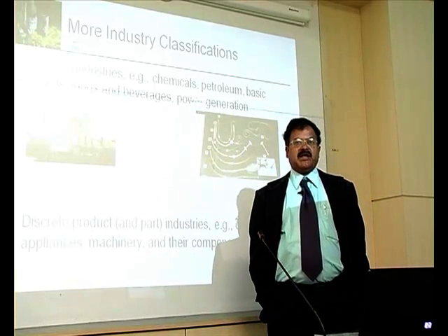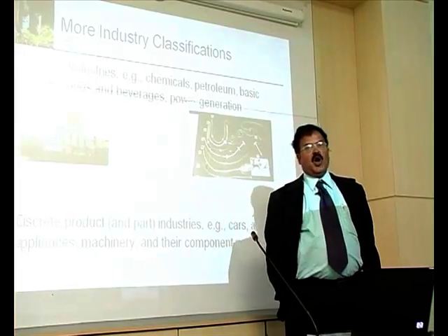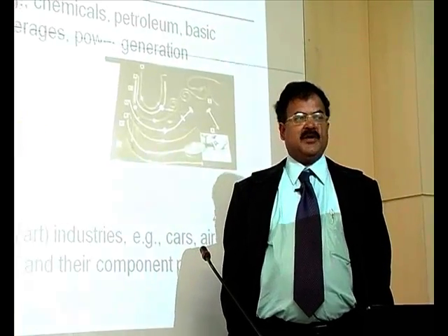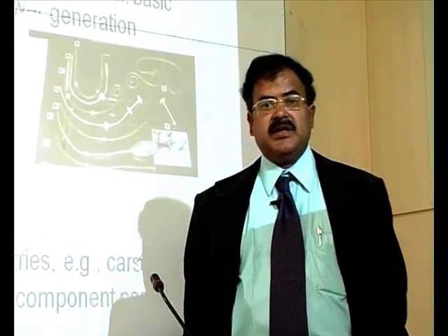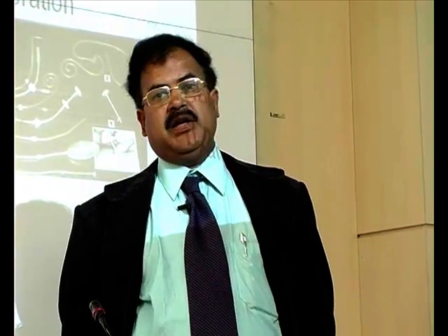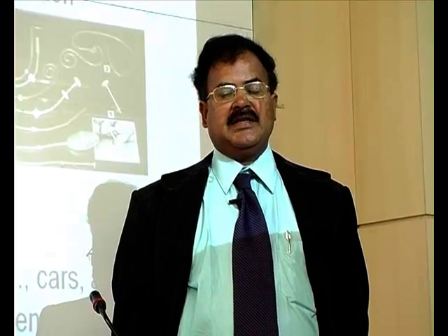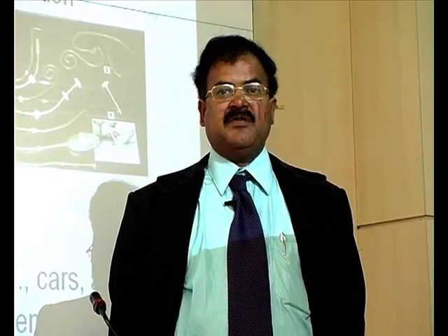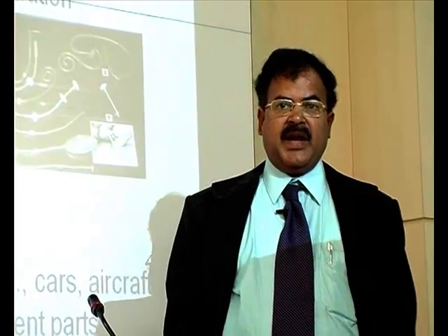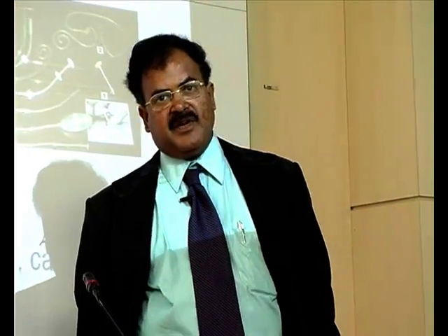How do we give the plant capacity then? Plant capacity is estimated as man machine hours. How many workers are working in that industry? How many shifts does that industry work? How many machines are working? And what is the total man and machine time available in one shift, or in a fortnight, or in one month? Like that, the plant capacity is estimated in terms of man and machine hours. So the quantification of plant capacity is different for process industries and discrete manufacturing industries.